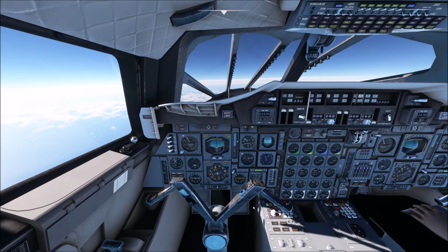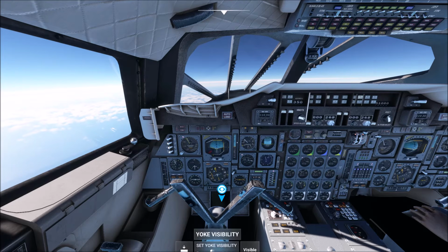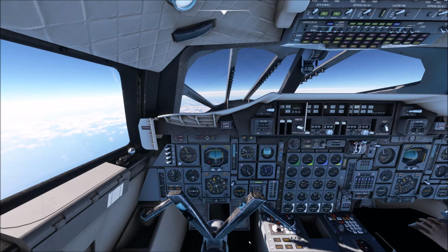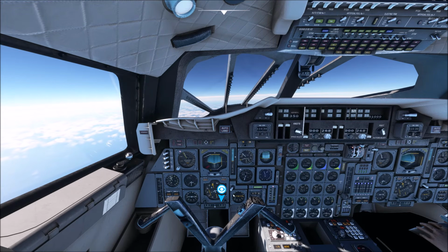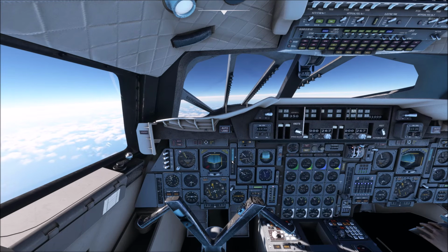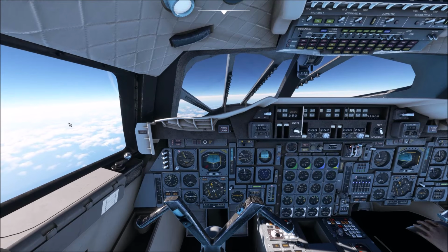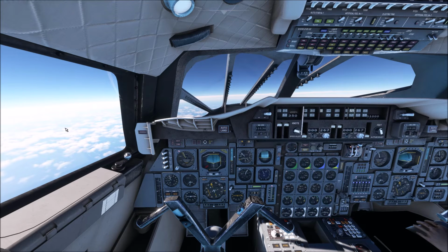Mach 1.8 coming up. No afterburners now, no reheat. Angle of attack just down to 1 or 2 degrees now, so we're quite efficient. Climbing at 1,000 feet per minute, that's a good rate of climb. You don't always see that. Normally at this altitude, this far into the flight, in the last week or so, maybe 500 feet a minute if you're lucky, sometimes as low as 200. Again, entirely dependent on how cold it is outside, what the conditions are, even headwind. How much headwind's coming at Concorde might make it difficult. But this is pretty good.